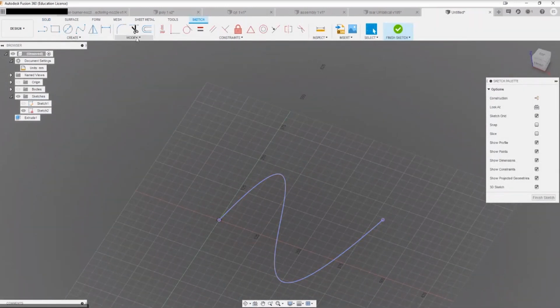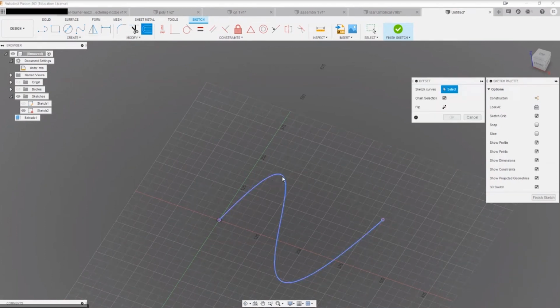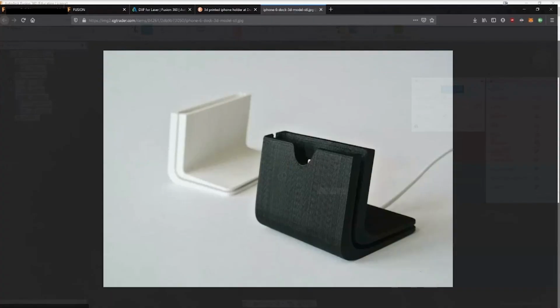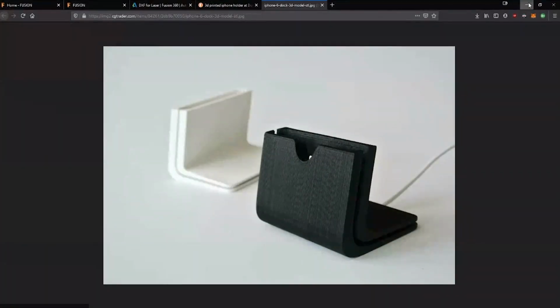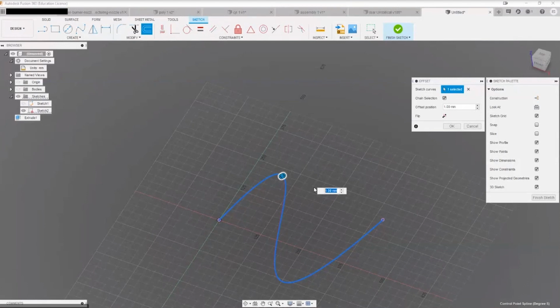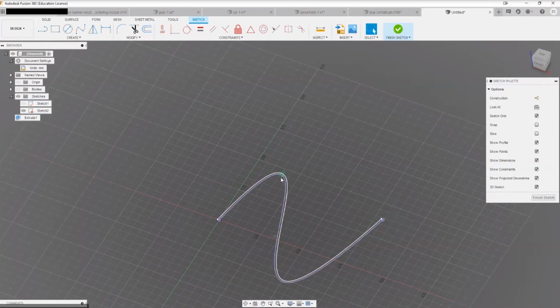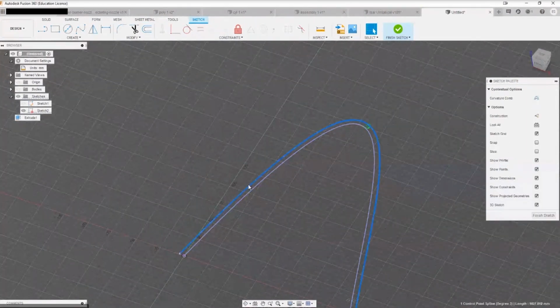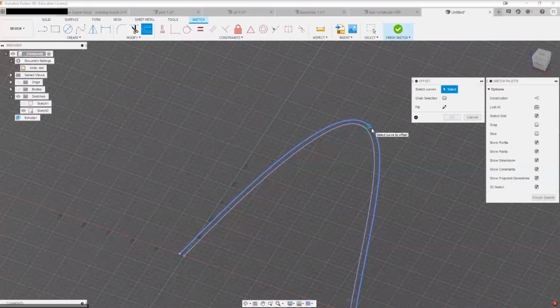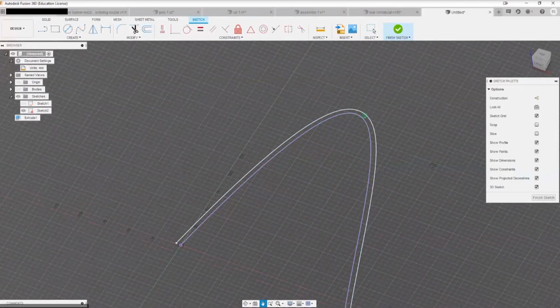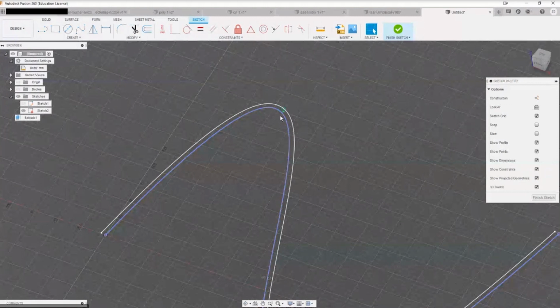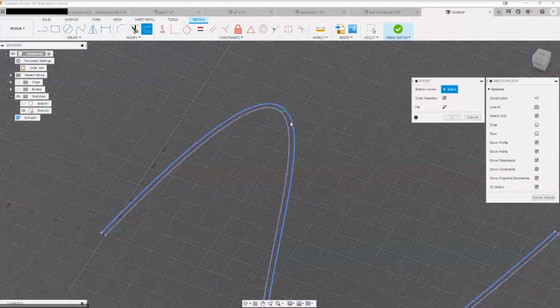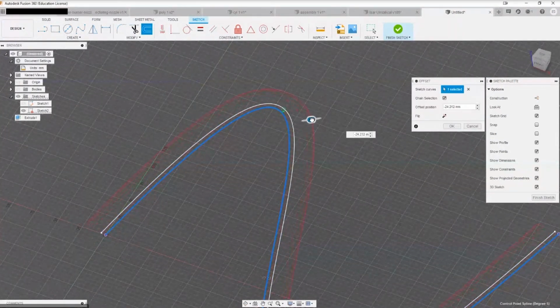So the best way would be, like on this iPhone, there's a little gap. Okay, so let's say our gap is going to be 5 millimeters. If you want it to go the other way, you can go -5. Let's say it's arbitrary. So you've got that there, and then you want to create something else that's something that's 7 millimeters thick. So you select the original one.